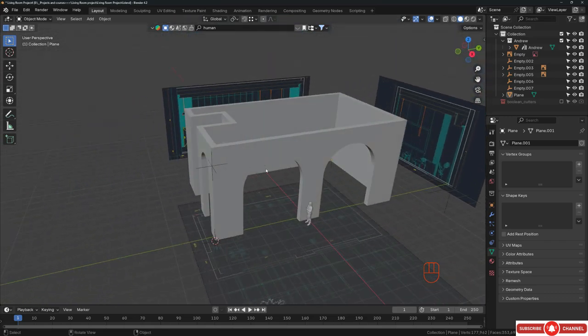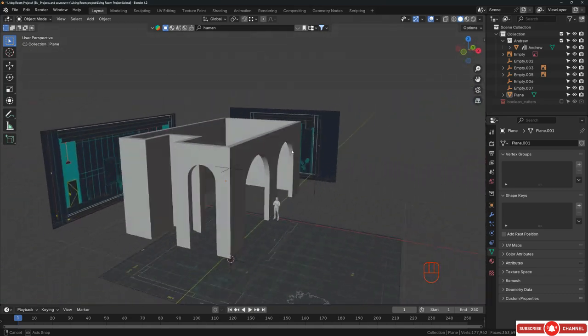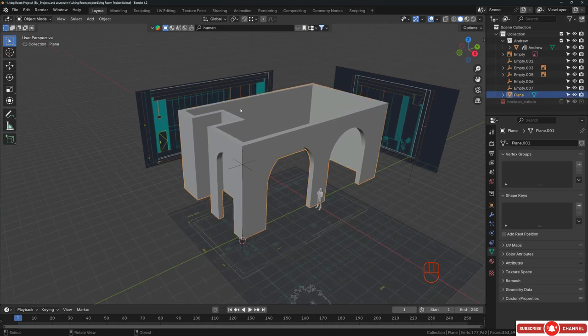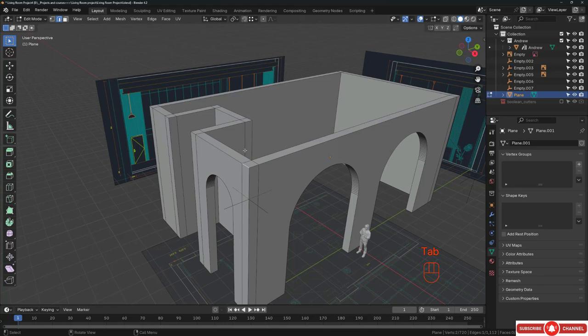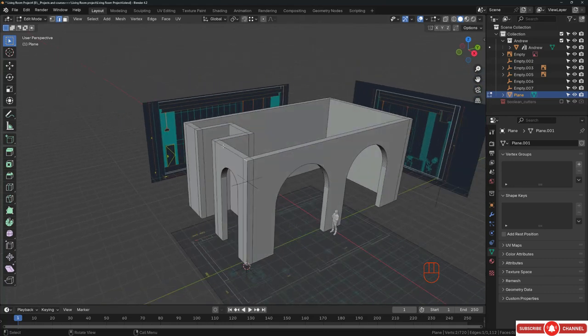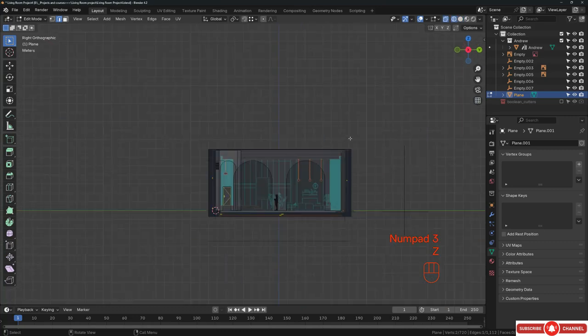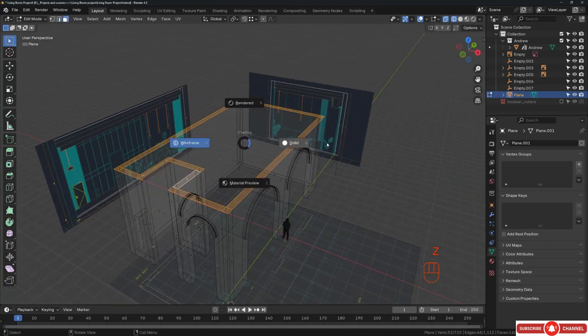After creating the floor, we can take care of the windows. I think that makes sense. So to create the floor, you can copy the faces we got right here, and we can use them. To select these faces, you can go to the side view, to the front view if you like, and hit Z to go to wireframe, and let's go to the face selection mode and select all of these faces like that. Now we have them selected.